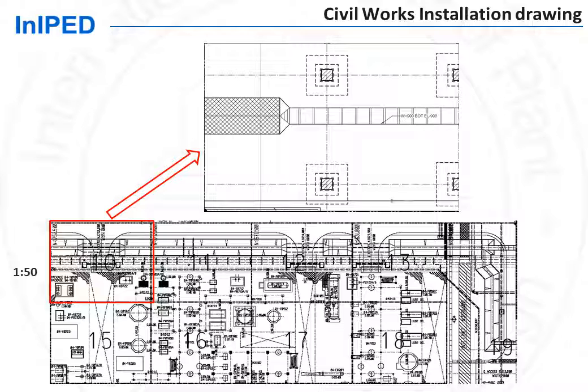The following revision will be the sewage branches and the firewater branches that come just on top of the headers. The following revision will see the cable trenches which come on top of these pipe networks. Finally, the last revision will show all the surface elements such as cable sleeves, pipe support foundations, small process drain lines, and so on.